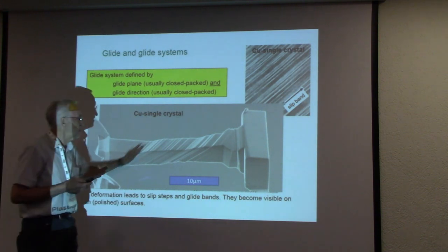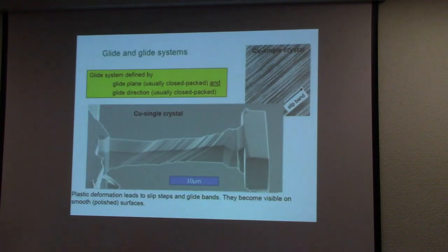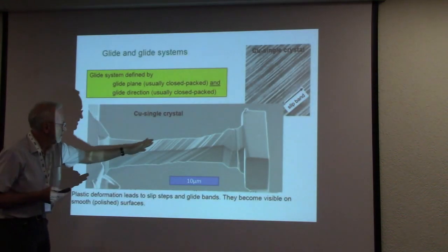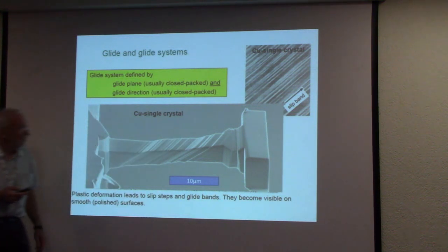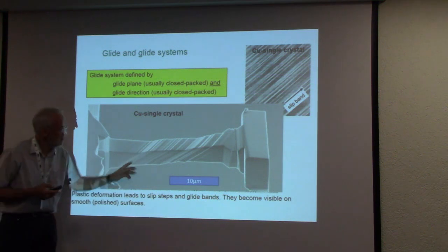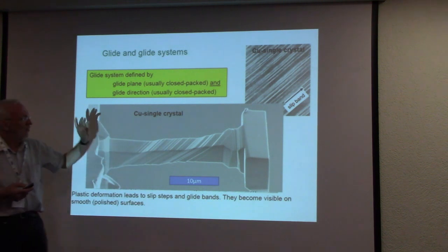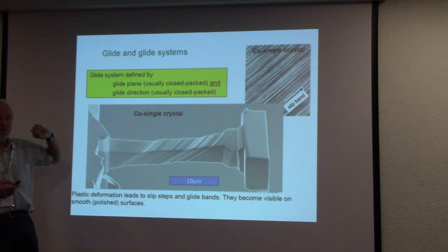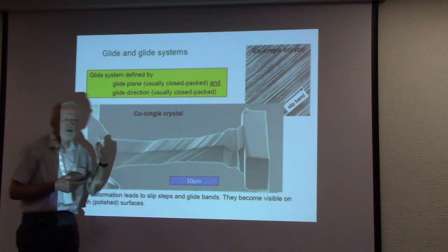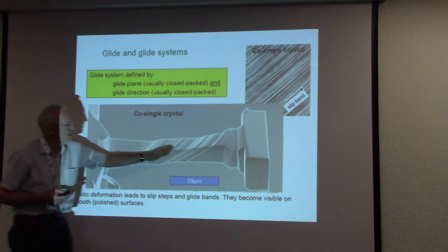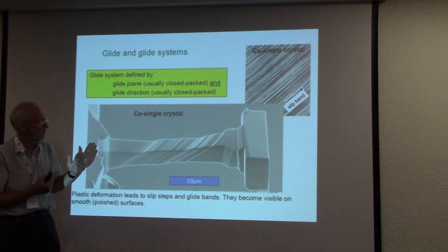So what happens is dislocations move on specific crystal planes. And therefore you can see here a tension loaded microsample, and you can clearly see that there are always a certain number of these Burgers vectors, these steps which form all this. And you see that this part of the crystal is not deformed. The deformation only took place on these special planes.